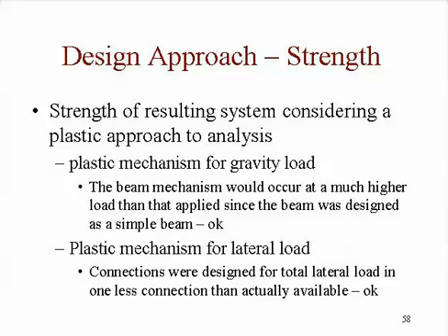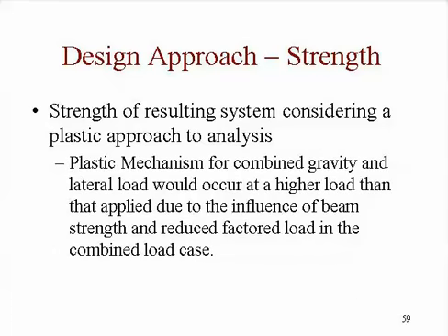If we look at the lateral load mechanism, we designed it for one less column, one less connection, if you will, than we actually have. And so, again, the lateral load mechanism should be good. And if we put the two of them together, the lateral load and the gravity load, if we remember that we have reduced factors on our loads, then you can show that the combined mechanism should be sufficient.